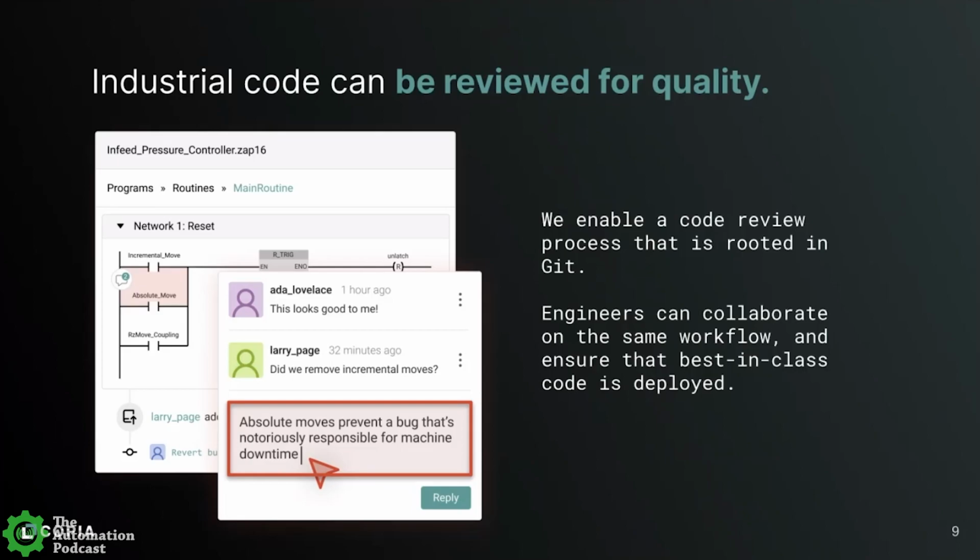In the Siemens example, they're using function blocks, and it's very much the same thing, where the diffs between the old and new program can be commented on by the people who are writing the code or by the people who are maintaining the code. So that's very powerful. You definitely want that. Just having the before and after really isn't too helpful. It's like having a PLC program without any documentation, right? It's like, well, why was this changed? You need that knowledge transferred into the system so people understand why this course of events happened.